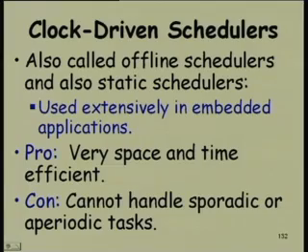The main advantage is that these are very efficient and take very little space. The scheduler component is nothing actually, it just consults something and finds out whether to stop the current task and start the next one. But the table will take extra space. So, space is a problem here, because we need to store the schedule, whereas in the event driven schedulers we do not store the schedule, but we will use space there for other purposes, such as storing the tasks that are pending, those that have not completed so far.